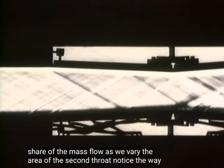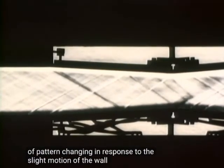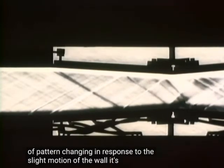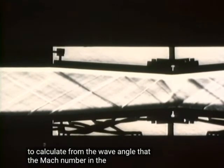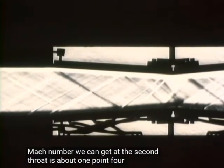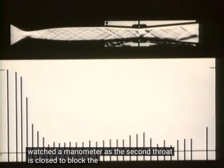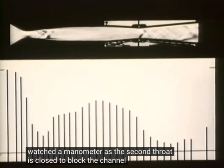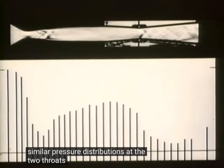We have to allow room for these thick boundary layers, which are not carrying their share of the mass flow. As we vary the area of the second throat, notice the wave pattern changing in response to the slight motion of the walls. It's possible to calculate from the wave angle that the Mach number in the test section is about 2.1, while the lowest Mach number we can get at the second throat is about 1.4. This time, watch the manometer as the second throat is closed to block the channel. Note the similar pressure distributions at the two throats.